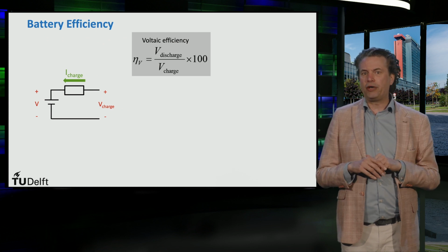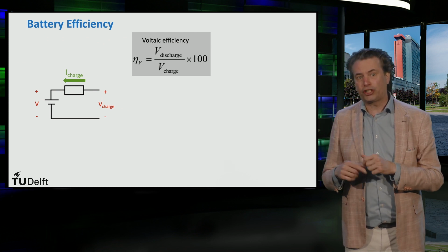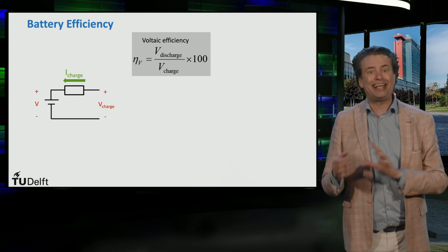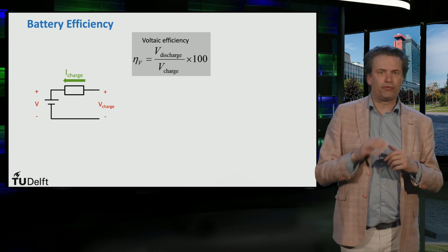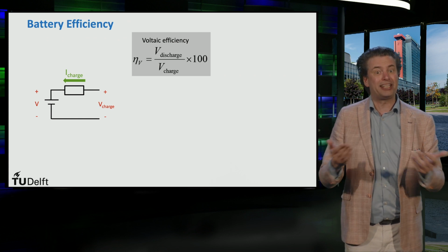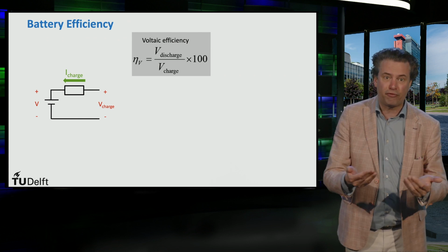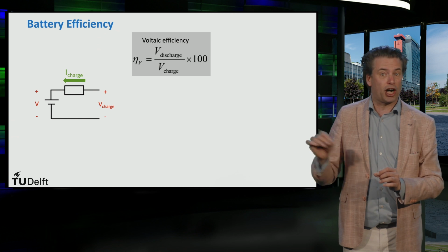But on the contrary, when the battery is being charged, the battery voltage will be slightly higher than its open circuit voltage. This is to compensate for the voltage drop that occurs inside the battery and to drive the reverse chemical reactions to charge the battery.